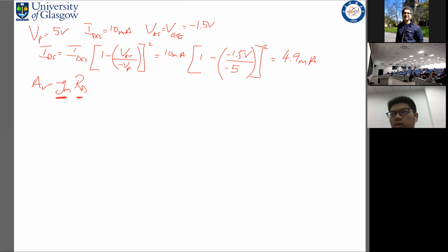So what is GM? GM is equal to minus 2 times IDS over VP times 1 minus VGS over minus VP. I'm sorry, I think I've forgotten a minus here.